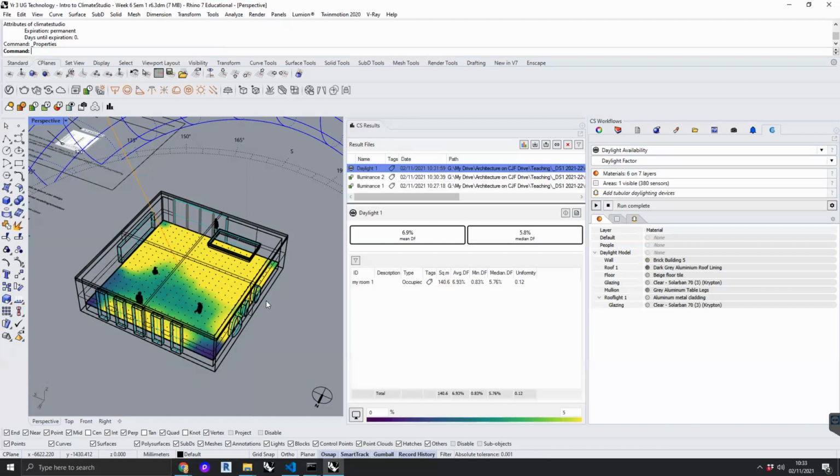It's huge. However, you could be in a place where there's lots of glass and almost all the light from outside is coming inside, like a greenhouse, for example. And then when you walk outside, it's like nothing's changed. So a greenhouse with completely clear glass that doesn't reflect any light at all would have a daylight factor of 100% if it was made purely of glass. What this is saying is that we've got a daylight factor of about 6.5, 7%.